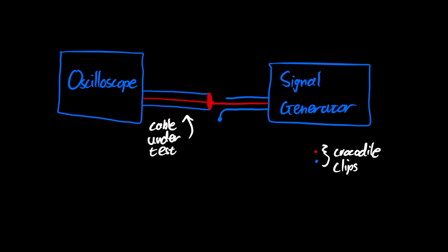At the oscilloscope input, the return conductor is electrically bonded to the metallic chassis of the instrument, which is bonded to the protective earth and its power cable. There's also 1 megaohm resistance between the center conductor and the return conductor.